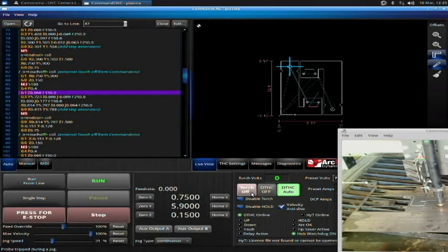Because in this next step, what I'm going to do is turn the plasma back on. If Command CNC was attempting to fire the torch, when I turn the plasma back on, the plasma would give me an error. It's like turning the torch on with the trigger pulled on the torch. The machine will not allow that to happen. It's a safety feature. Okay? So I would get an error on the front of my plasma.